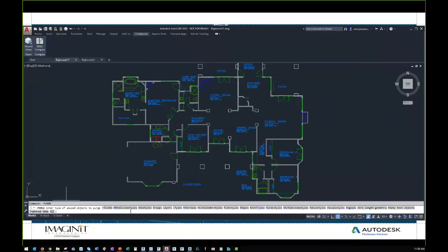And are there still issues with saving a DWG file backwards to older versions and maintaining the full extended data? If you're talking about Civil 3D, then yes. We were still not able to just save back a file from Civil 3D to a previous version. Like 2018, 19, and 20 are all cross-compatible, so you're just doing a standard save there, and you should be able to open it in any file. But if you are working with Civil 3D 2017 or 16 or 15, you cannot just save back and expect it to work. You're stripping it down to the standard AutoCAD objects at that point.